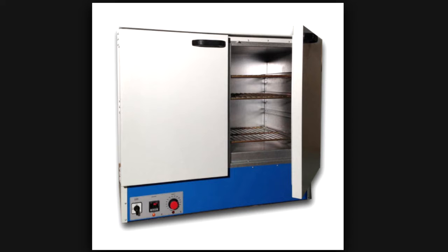The group then waited a day to remove the samples for both fine and coarse aggregates from the oven. The samples from the oven were weighed and were compared to the original samples to calculate for their respective evaporable moisture content.